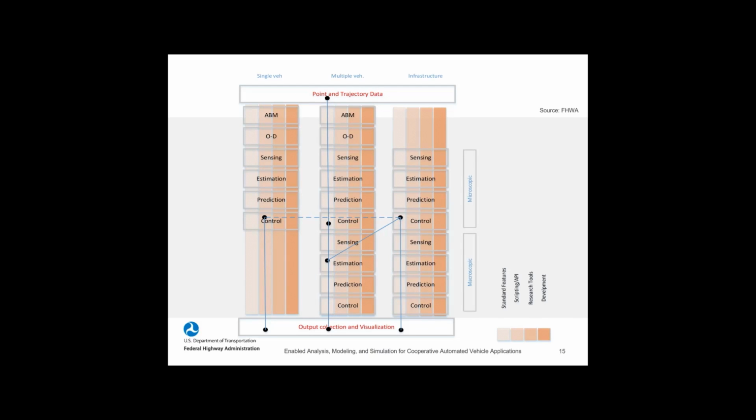So it looks like this in terms of that pillar diagram. If you look at the single vehicle, I am putting in the control at the microscopic level because I need to be able to adjust the behavior, the control behavior of the CAVs to do the eco-drive. And I'm putting it at the scripting API column. And that's because, yes, you can use Vissim to put CAVs, but they are going to just drive normally within the traffic with the CAV parameters, of course. But they are not going to do eco-driving with the signal. So we need to use API to do that.